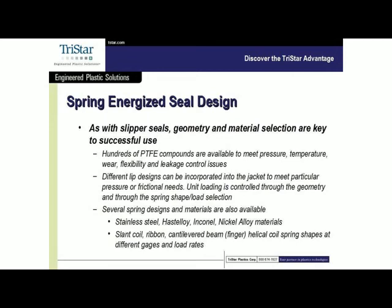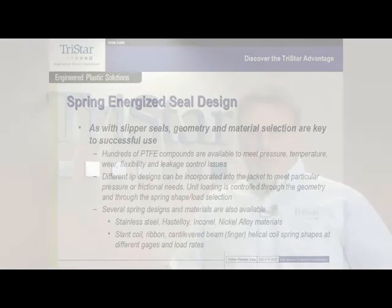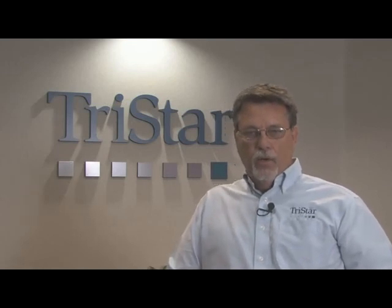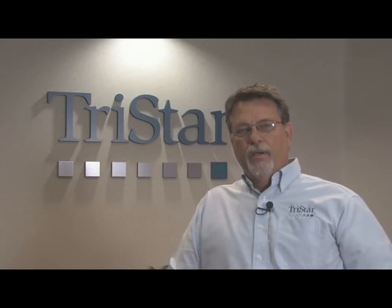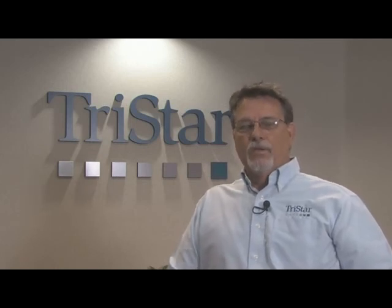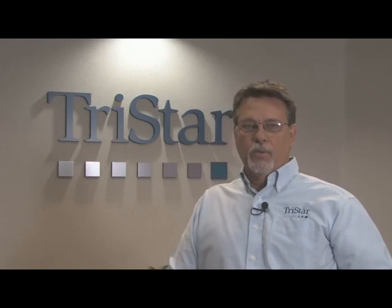We have different gauges of spring, so there's different forces being generated. The shape of the spring, the location of the spring compared to the seal footprint area, all of this comes into play designing a spring energized seal. We have a lot of different spring designs and materials. We can make springs out of stainless, a couple different grades of stainless, Hastelloy, Inconel, nickel alloy materials. We have slant coils, ribbon springs, cantilevered beam or finger springs, rosette springs, helical coil, and all different gauges and loads. So a lot of variety can be introduced in both the jacket design, the jacket material, and the spring design and the spring material. All of that comes into play as we look at spring energized design.